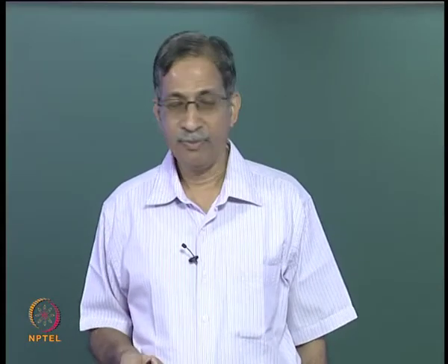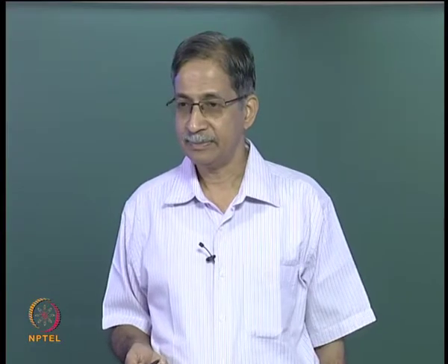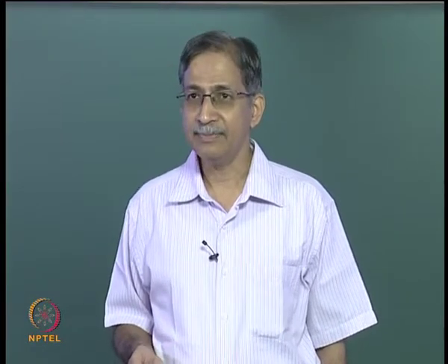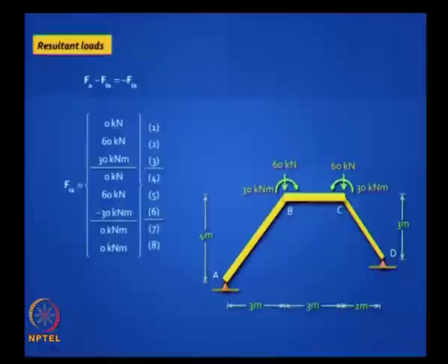You have got the load vector. What do you do next? Right, you can draw a sketch. Look at this. This is your resultant load vector. FA minus FFA. FA is a null vector because there are no nodal loads in this particular problem. You had only a UDL, and so FFA is given there. Put a negative sign to it and interpret those results.